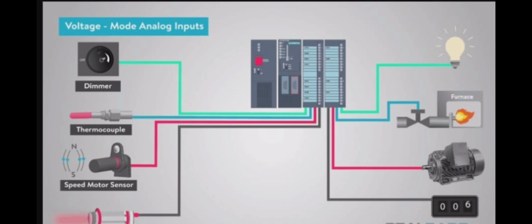what is the condition of the valve, whether it is fully open, partially open, or closed. Now, let's dive into the analog output signal. As I said earlier, the valve operation. It means the valve opening and closing condition is shown by the 4 to 20 signal, which is in the form of analog output.